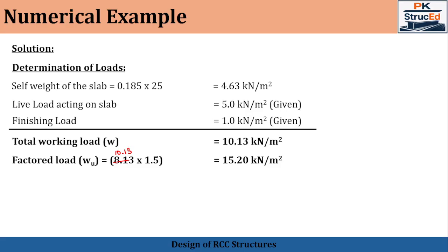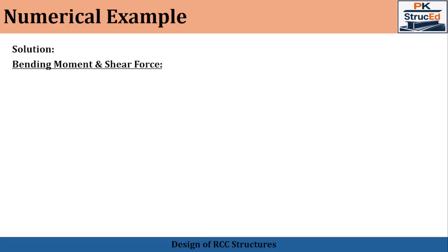Now, don't forget, in slab design, all loads are considered per unit area, unlike the beams. And next, the bending moment and the shear force. In two-way slab design, bending moments are calculated in both directions, not like in a one-way slab where we'll be calculating along the shorter span direction alone. Here, the moment coefficients will be obtained from IS 456 tables.